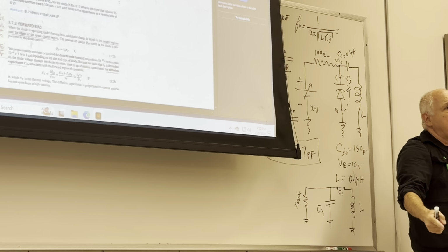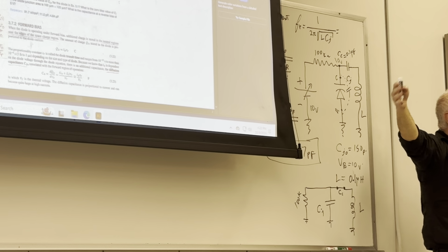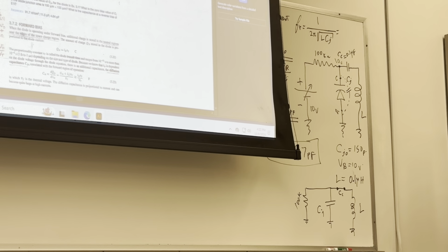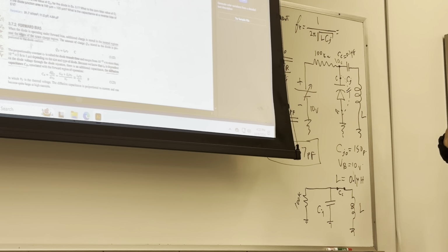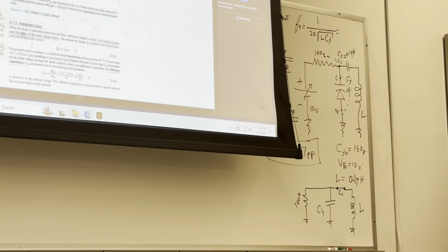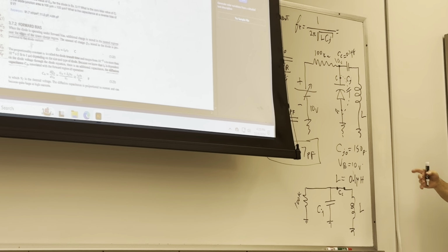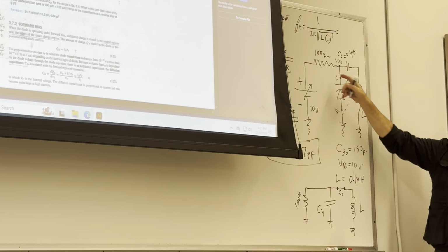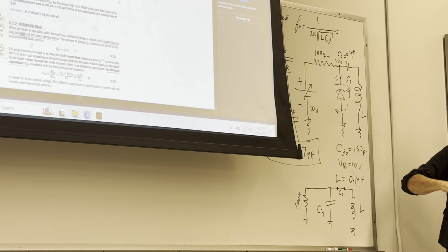Boom, breakdown. So the high end, how high you can go, will depend on where the diode breaks down. So it's a limit. 30 volt, 40 volt, 50 volt, they go up to about 40 something volt. So there's a limit how high you can take that voltage in order to reduce the capacitance.